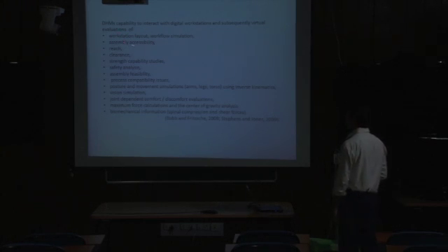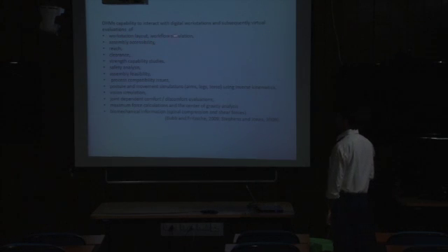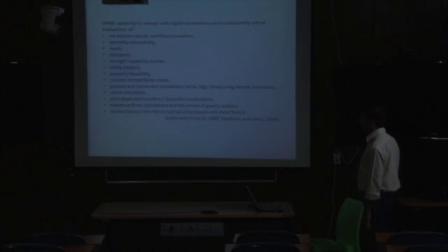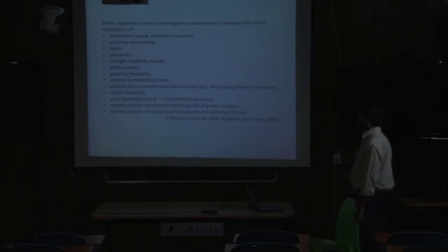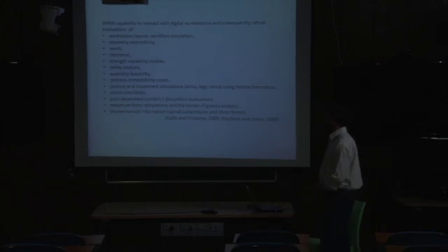As ergonomic evaluation, they mention we can study workstation layout, workflow simulation, assembly accessibility, reach analysis, clearance analysis, strength capability studies, safety analysis, assembly feasibility, others like process compatibility issues, posture and movement simulation for various body part movements, then inverse kinematics, forward kinematics, different types of kinematics for posture, giving the appropriate working posture or simulating various types of tasks, then vision simulation, then comfort analysis based on single body joint or multiple body joints, then maximum force calculation and center of gravity analysis,